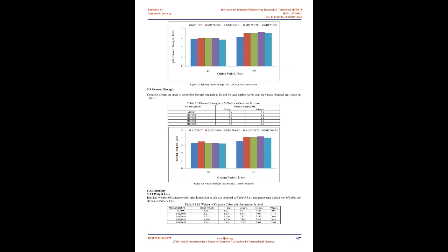2.0 Research significance. Cracks in a concrete structure reduce the life, and cracks of dimension smaller than that of cement, micro cracks, cannot be filled with chemicals. Crack treatment processes involve harsh materials such as cement and chemicals, adding to the pollution of environment. There have been instances of allergic reactions due to chemicals faced by the inhabitants and handlers. Bacteria secrete calcite which fills the cracks, and compressive strength and durability of concrete is improved.